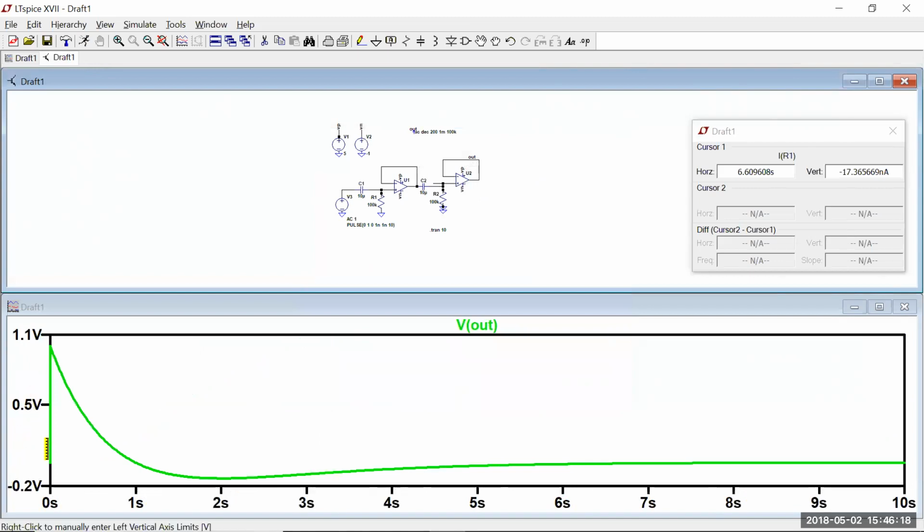There is our almost instantaneous change, exponential decay. It does shoot below zero once and then settles. So that is definitely indication of a high pass second order, critically damped, near critically damped. Could be a little under damped, could be a little over damped. A damping coefficient of 1, 0.9, 0.8, or 1.2 can be very hard to tell by eye.